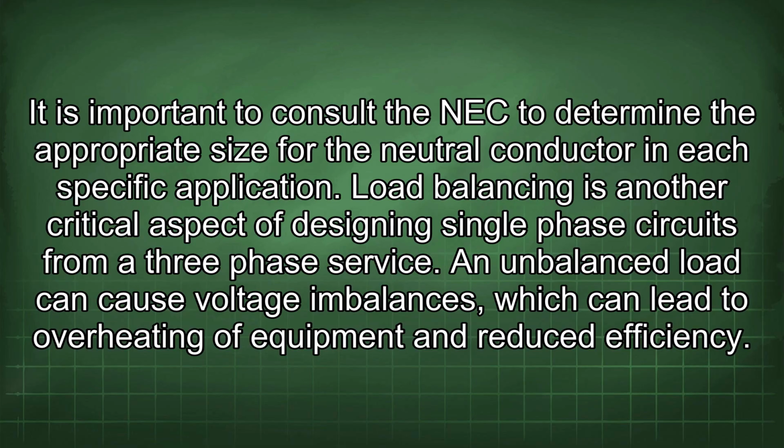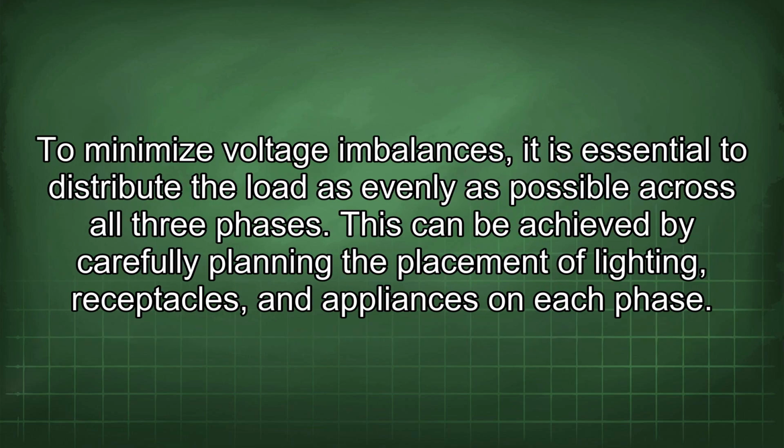Load balancing is another critical aspect of designing single-phase circuits from a three-phase service. An unbalanced load can cause voltage imbalances, which can lead to overheating of equipment and reduced efficiency. To minimize voltage imbalances, it is essential to distribute the load as evenly as possible across all three phases. This can be achieved by carefully planning the placement of lighting, receptacles, and appliances on each phase.